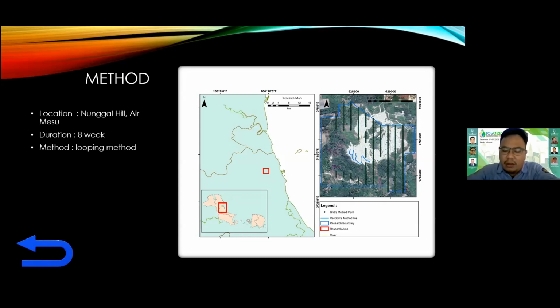After the data correction is done, we can obtain pure geomagnetic data that is usually referred to as total magnetic intensity, or TMI. This TMI will then be filtered step by step to obtain the maps that I mentioned earlier, which show various colors representing various geomagnetic values.